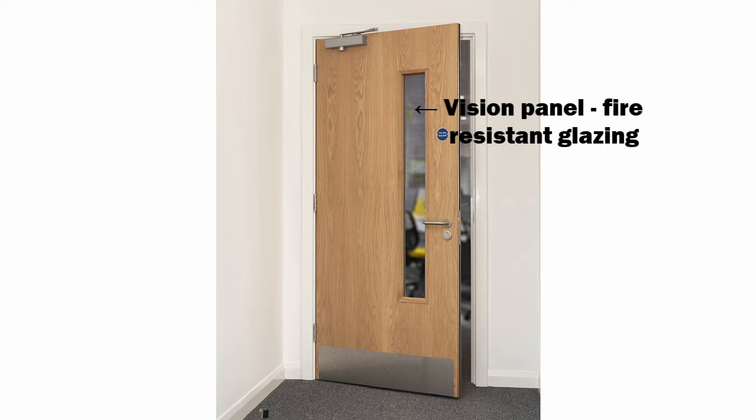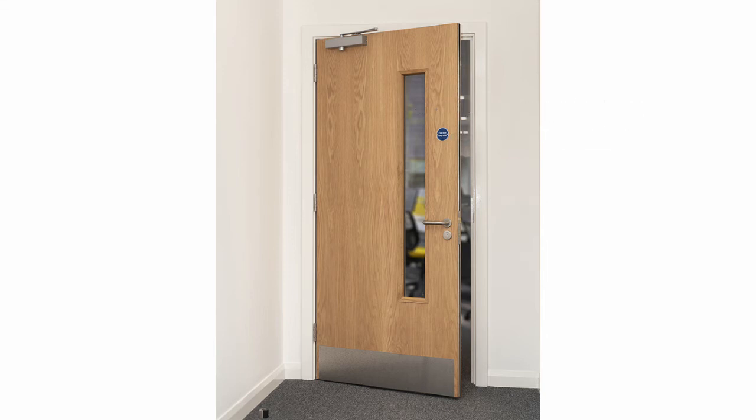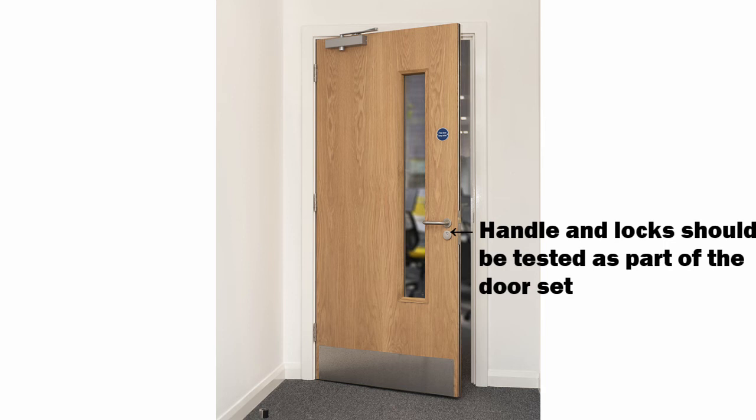The first step for the manufacturer is to construct a fire door set designed to a specification that, in their opinion, will resist a fire for a specified length of time. This door set will then be tested by an approved fire door testing centre, and if it is passed, any door sets constructed to that specification will be considered for certification.